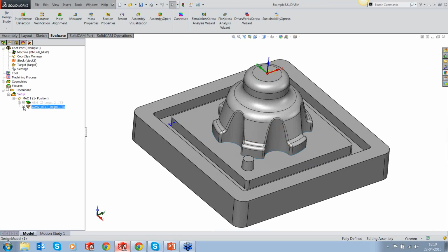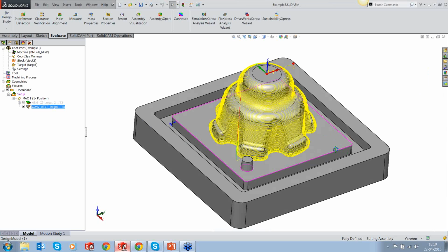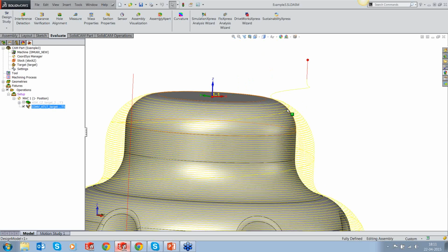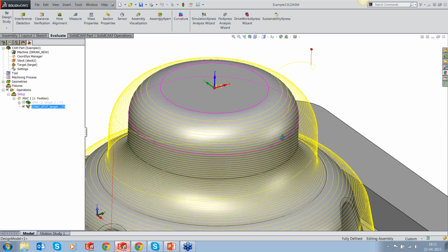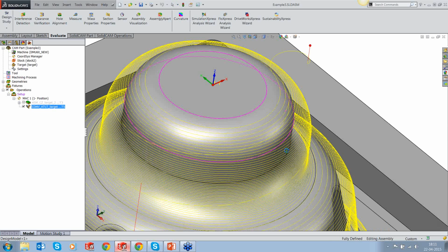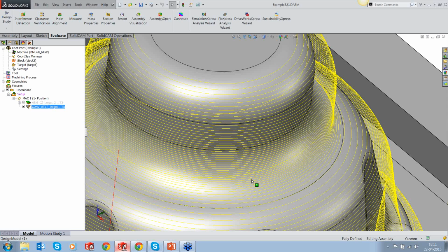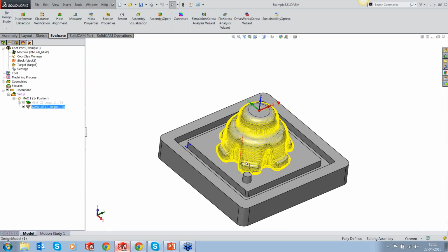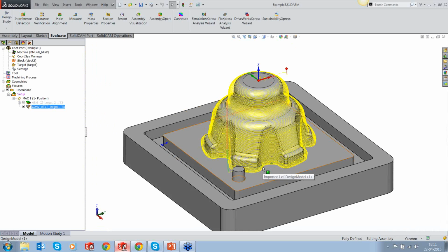All right, so the tool path has been recalibrated. You can see that none of the links were touched. It's the same link, okay? It's the same HSM link. It's the same HSM connection that it is using. Nothing was done. The only thing that was done was it recalibrated itself to provide a 5-axis tilt whenever the holder is coming in close contact with the part.